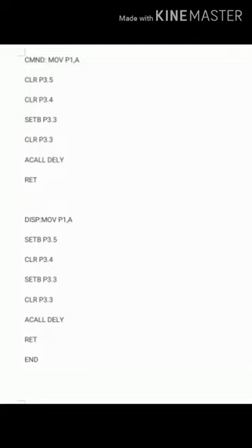If it is 1, the LCD will get to know that the data sent from port 1 is display data, and therefore the data which it has collected from port 1 on DB0 to DB7, it will store in the data register, and the moment it stores it in the data register it gets displayed on the display unit.